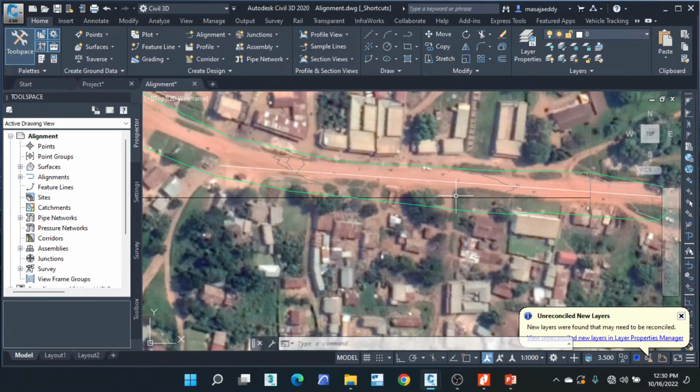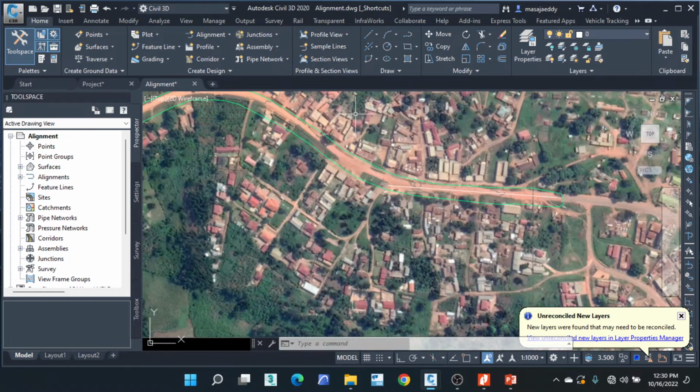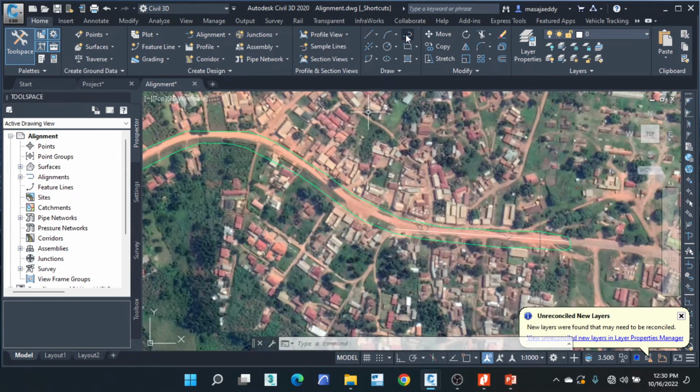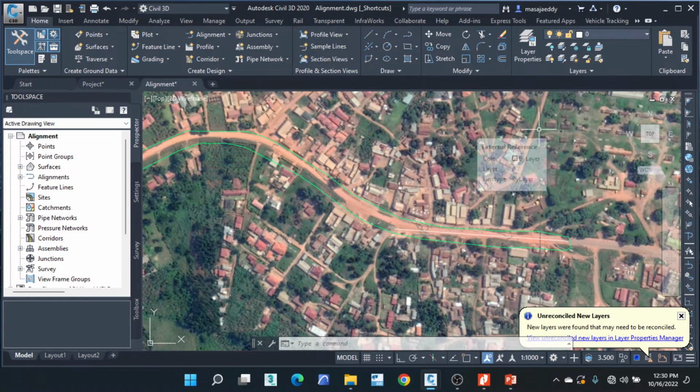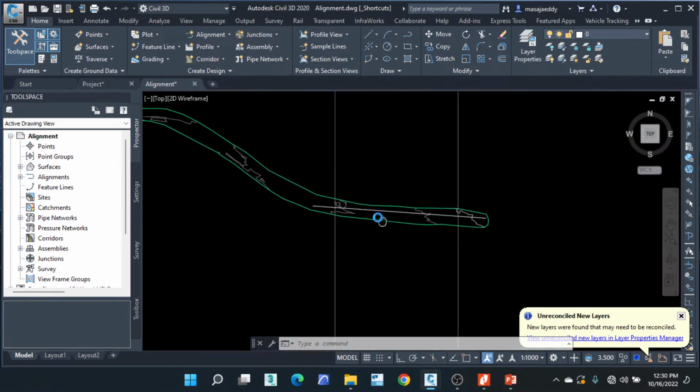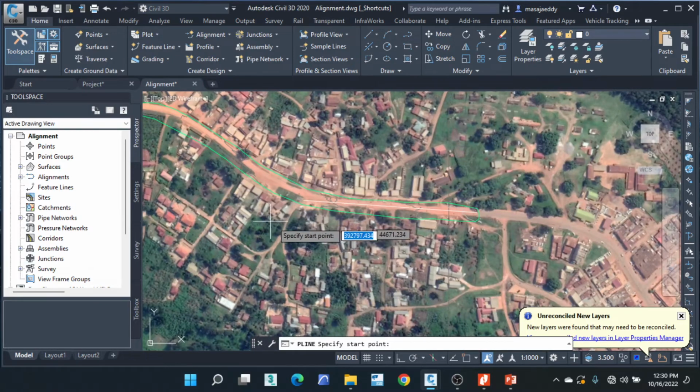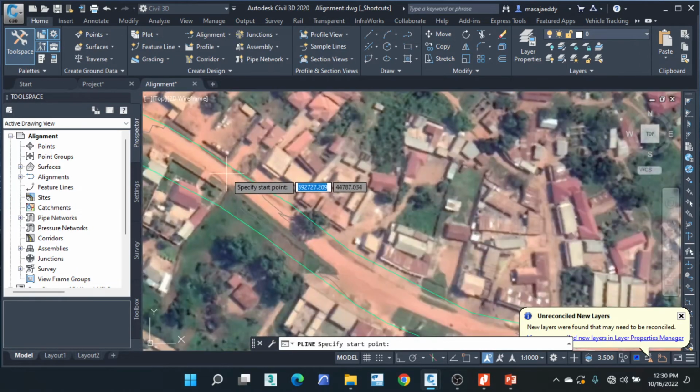We use polylines. This is one method of route planning. You can either use the tangent method or the arc method. With the tangent method, you identify your straights first, and after you join them with curves. Yeah. There's another one here.